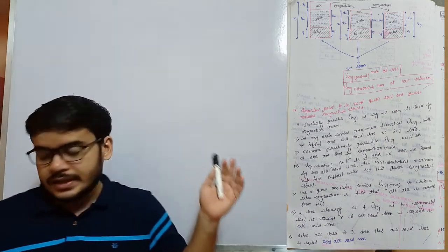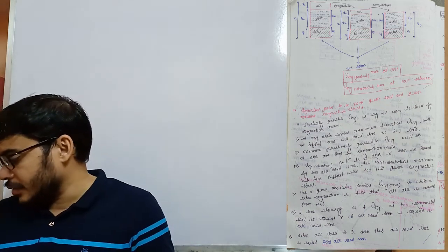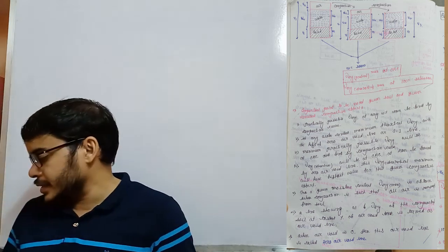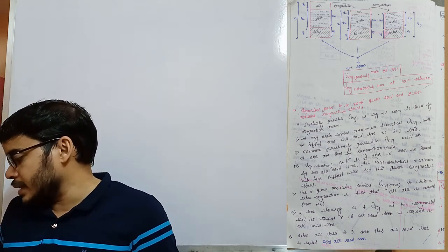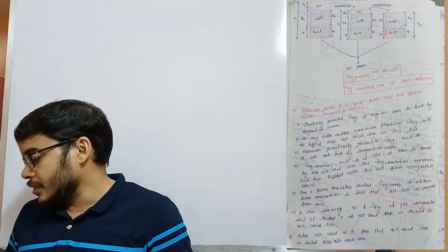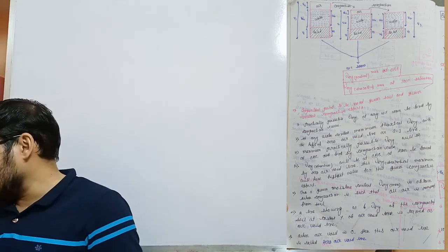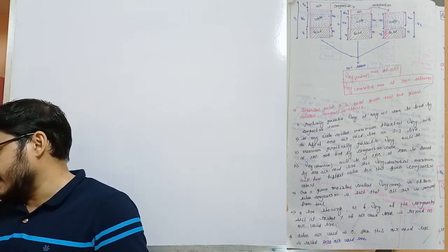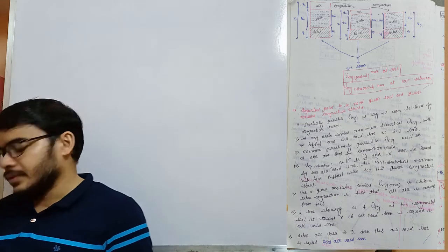And now some points are important here. Write all of these points very carefully. Important points to be noted, for the given soil and given constant compacting effort. First point, practically possible gamma dry at any water content can be found from the compaction curve.